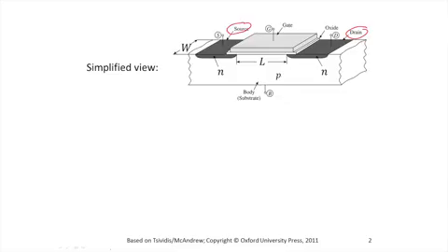On top of the P-type region, we have grown an insulator, typically silicon dioxide, and often referred to simply as oxide. And on top of that, we have a conductive region called the gate. Typically, the gate is much taller than what I show you, but for economy of space, we will show it as a shallow region.